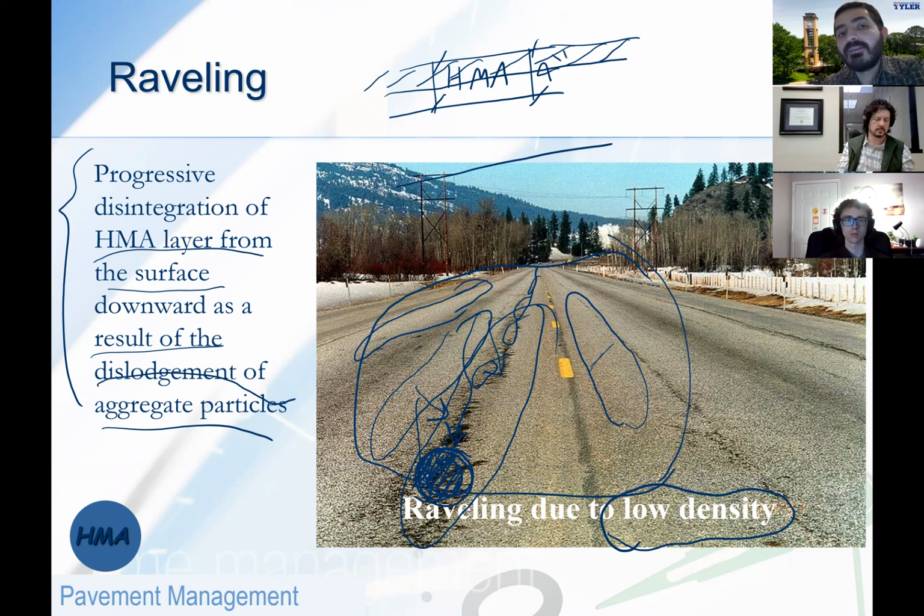So it depends again on the severity of the structure. It can go as low as a seal coat or as bad as removing the whole thing. But typically, the more frequent solution that I've seen over the years is a mill and fill job, where you remove the top couple of inches where the problem is, prevent the problem from extending to the rest of the structure, and then repave that top 2 inches.